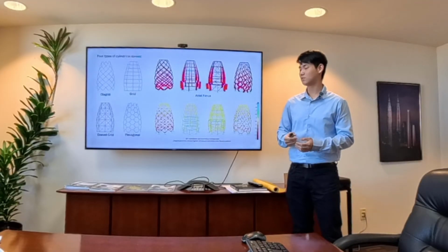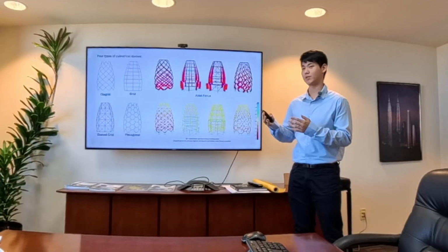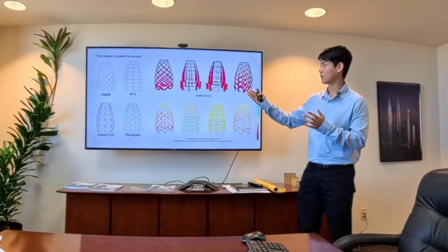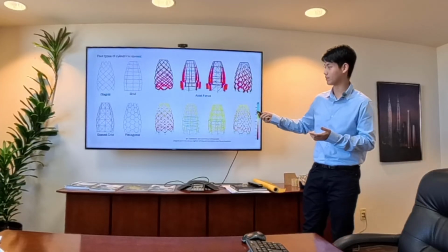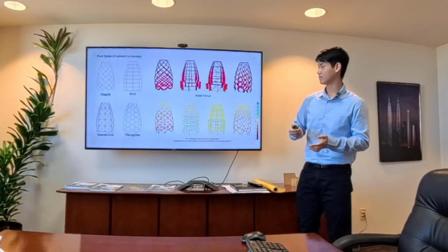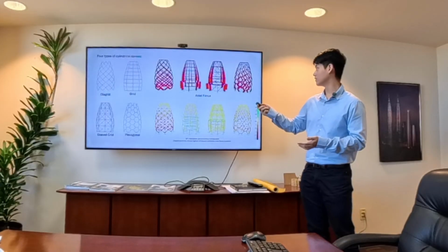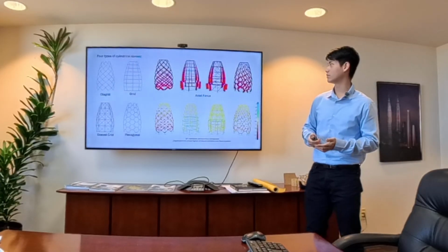And after that, I wanted to see more of the structural differences that can occur when varying the outside frame of it. So I changed up the different domes into digrid, grid, raised grid, and hexagonal. And with the structural analysis, I observed how the axial forces reacted and the stress distribution between all the designs.